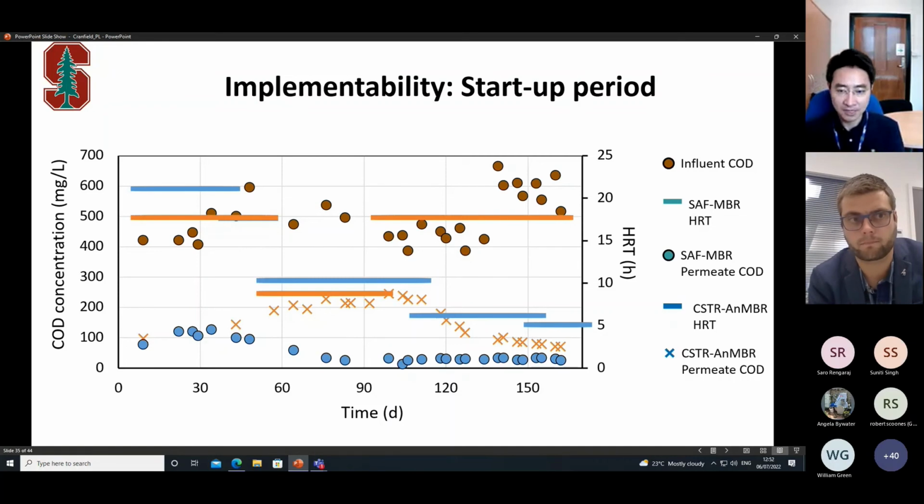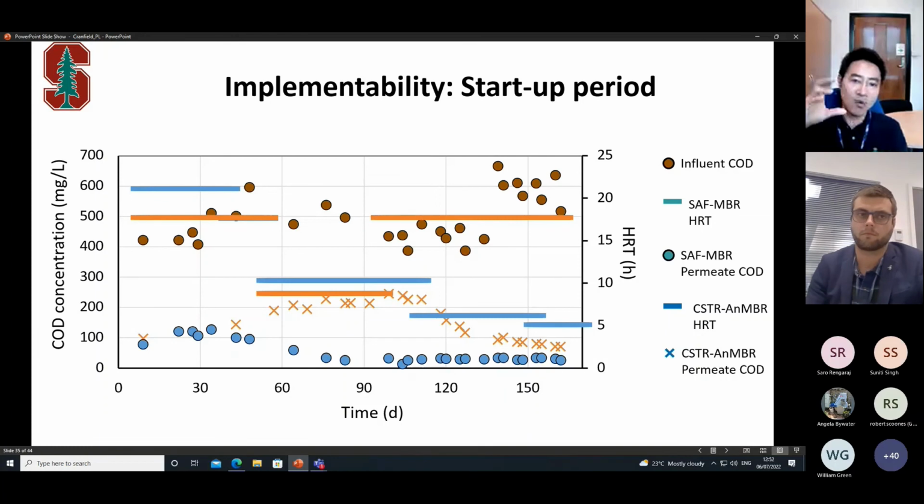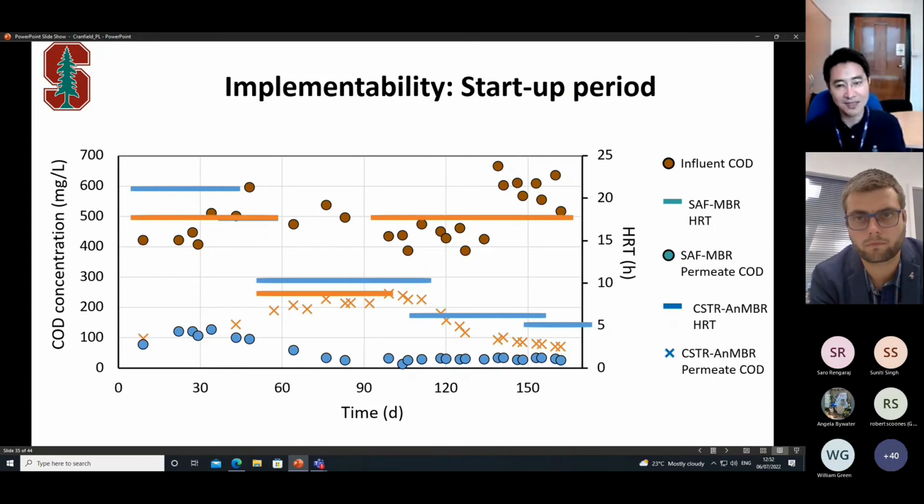That might be better, because hydrolysis is so difficult. You can separate solid and liquid more, and you also get more AD digester sludge, to produce more methane on that side. Then in the liquid part you use a short HRT, so you can shorten the footprint. So you can have a pretty good balance.